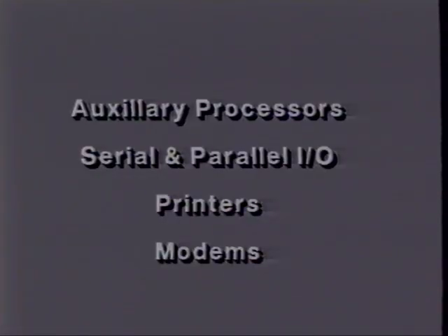The last class of programs are those that we call peripheral diagnostics. This covers a wide range of tests, including auxiliary processors, serial and parallel I/O channels, and external devices such as printers and modems. Before assuming that a unit is working, test all peripheral functions. If a unit that came into your shop for a memory failure also has a serial I/O problem that you do not fix, you may have to repair it later, and you certainly won't have pleased the customer.